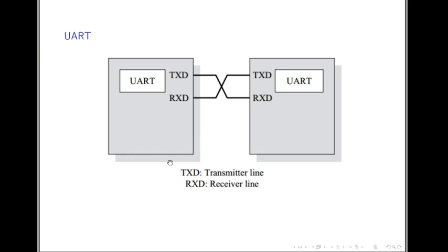And the third is UART. It is an asynchronous form of transmission, where the transmitter is connected to the receiver of another device and the receiver is connected to the transmitter of another device. It is asynchronous, so parameters like flow control, baud rate, and signal level are predefined, and based on those predefined parameters the data is ensured to pass safely and correctly without any error. Errors can occur, therefore we have some redundant bits to check for errors.